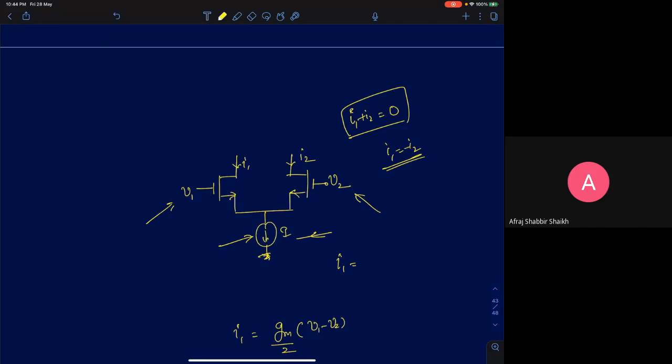Yeah, we discussed the spectrum and all that, but right now we will look at a much simpler characteristic. We just derived, if this node voltage is V1 and this node voltage is V2, what is the small signal node voltage here? We just derived an expression for it. Can I say it is V1 plus V2 by 2? It's the average of the two, which is V1 plus V2 by 2.